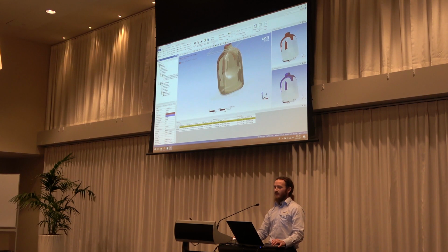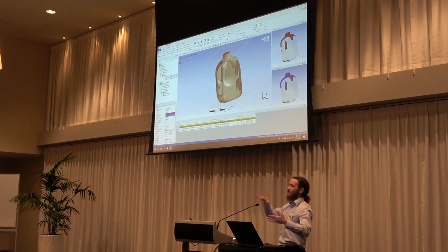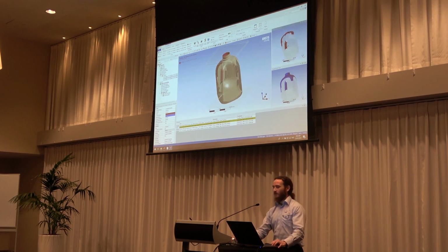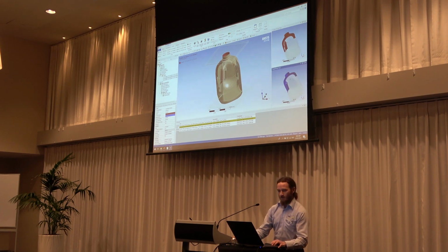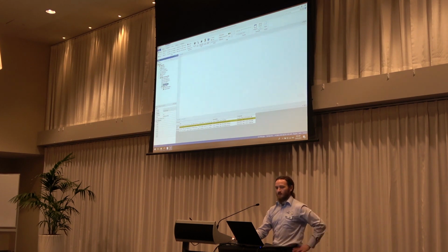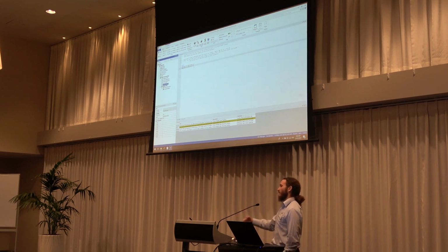And because this is a crushing analysis, this is going to undergo self-contact. So as it bends and buckles and folds over itself, it's going to contact itself. So I've defined this contact between identical surfaces in the contact and target. That's that. Mesh, all good. And let's just hide this so we can see it a bit better. In the command object, I've got semi-implicit. That basically activates it. I've specified the time step size I want to use, so it'll activate a bit of mass scaling, and by default it wasn't writing as many result steps as I wanted, so I told it to write a few more. That's basically it.